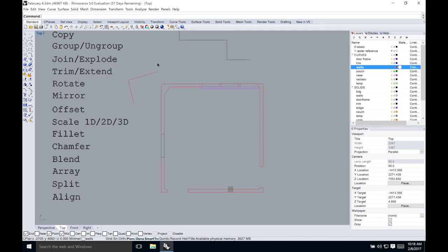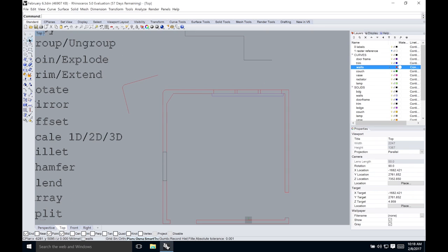Then the blend command, which also has a three-dimensional version, is very handy when you have curves, and they can be straight or freeform curves, but they aren't connecting. Sometimes when I use this, I somehow have, let's say, contour lines for a site plan, and for some reason, from wherever I got the data, the contour lines are made of segments and some small pieces are missing.